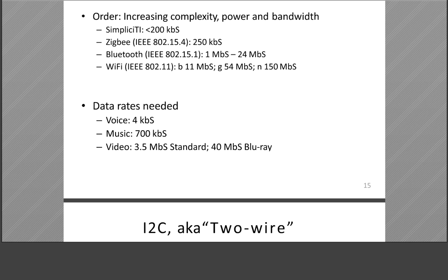KSPS means kilo samples per second. But each sample, for example in standard telephony voice, is from an 8 bit A to D. That means each sample is 8 bits.